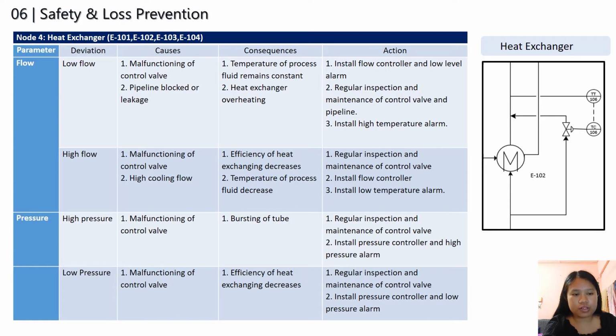And for low pressure, the causes could be malfunctioning of the control valve as well. The proper actions that should be taken are regular inspection and maintenance of the control valve, installing a pressure controller and a high pressure alarm, and also a low pressure alarm.